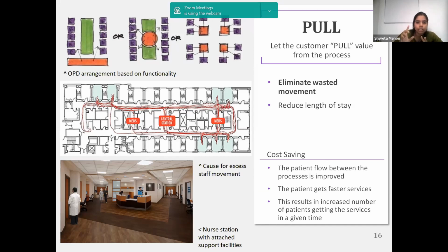Plus, they've got certain stores in awkward corners. When we've got an awkward corner where an IP room can't fit, we'll end up putting a store over there. So a store over there, or a sterile supply unit somewhere, a dirty utility somewhere. The problem by doing that is that nurse has to now travel to one room, and then from there travel to a store, from the store travel to another utility place, go to another medicine place, get back to the room, go back. That is a very long route for that particular nurse.